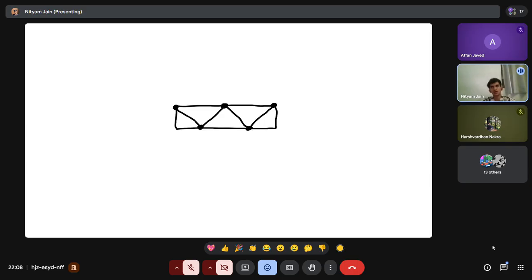In any truss, you would have seen that all of the steel is welded together, but conceptually they act like pin joints because the member sizes are so small that when the loads act, it can literally rotate a little bit. Just imagine having a thin steel wire in your hand and you want to bend it. So it would kind of act like that. It's not a little pin which is there, but that bending allows a pin joint sort of behavior.